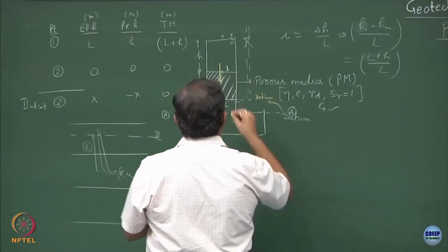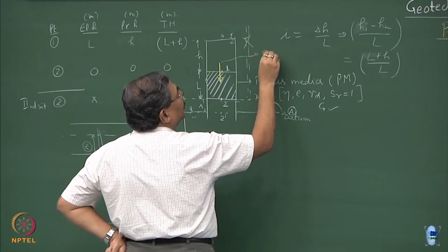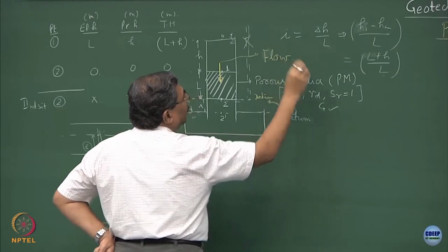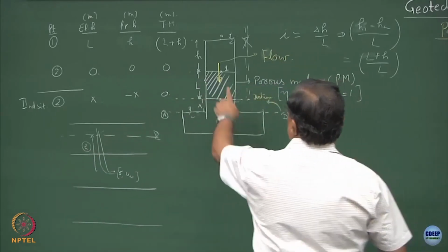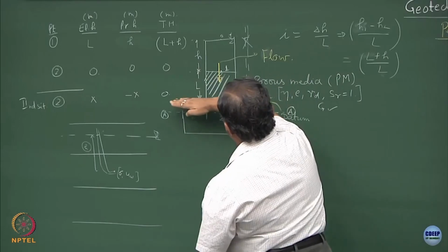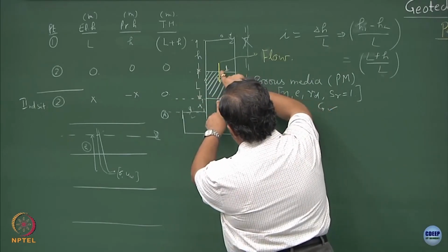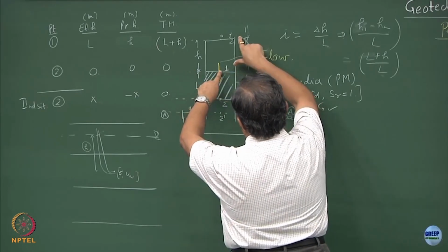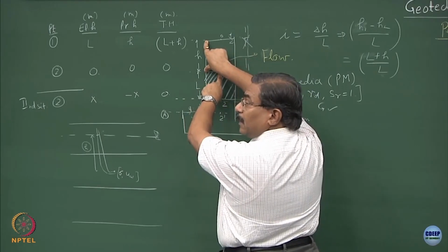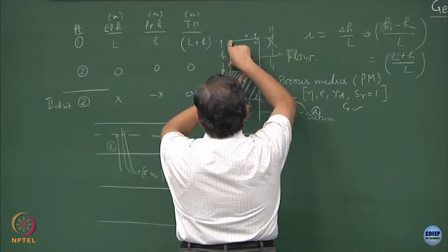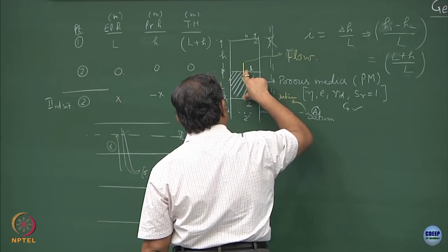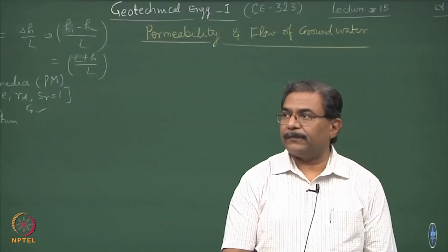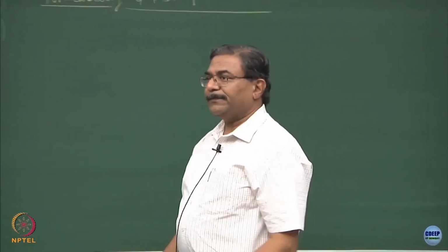So, this yellow arrow shows the flow through the porous media. Where? Point number 1, elevation head. See, if you fix the datum over here, this is the elevation head at point 1, this is L. If you put the piezometric tube over here, it meets up to here, so L plus H, clear. So, pressure head is H at this point, elevation head is L, total head at this point is L plus H, fine. Have you understood the discrepancy?